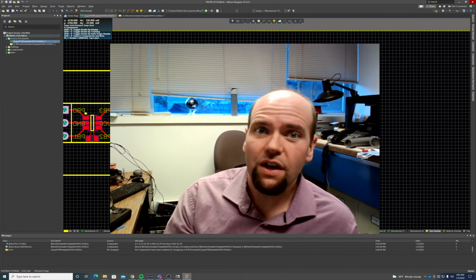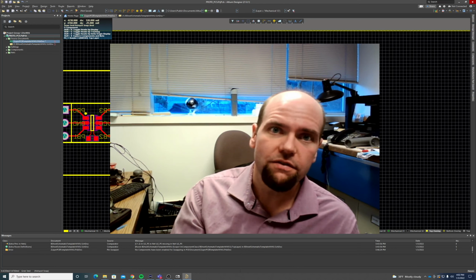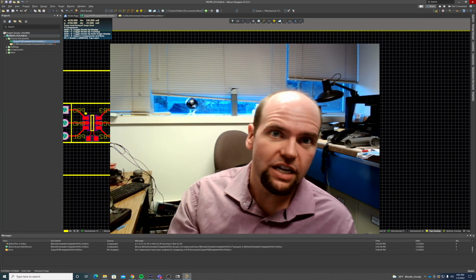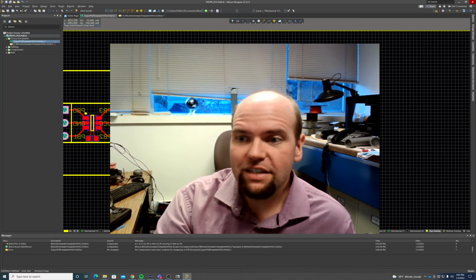It should be easy with other EDA software. It's easy. With Altium, it's not. So if you want to make 7 copies of a certain footprint for a chip, as a last step, you can make a bunch of them. You can export it for fab, and it'll be okay. But you do it as a last step because it doesn't play nice with Altium.